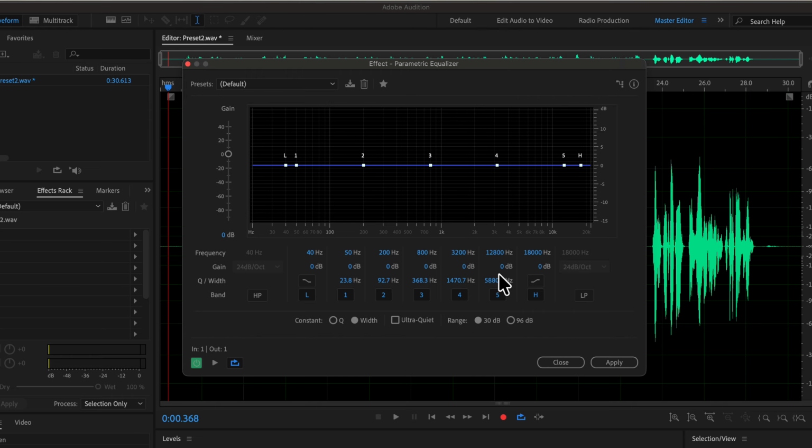Okay, instead of knowing the theory, let's see a practical demonstration. We will use a specific EQ that is called a high-pass filter, and that is denoted by HP here. I will click on the HP. You can see that once I activated the high-pass filter, it cuts some frequencies here, and we can actually control at which frequency the cut occurs. I'll play the audio, and I will move this frequency. When I do that, the curve will move, and you will see the audio tone change.